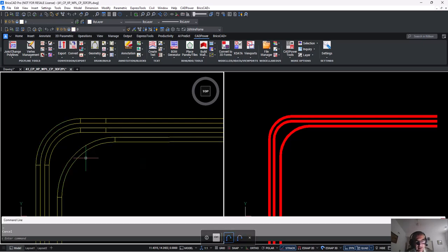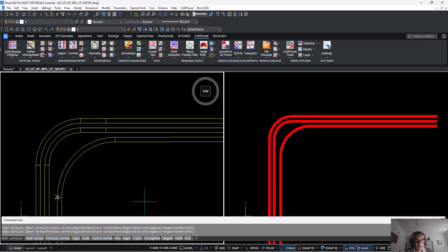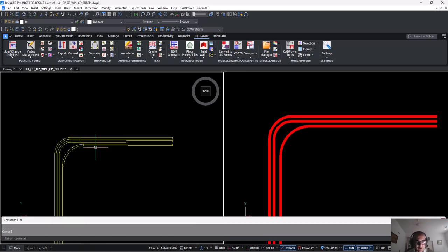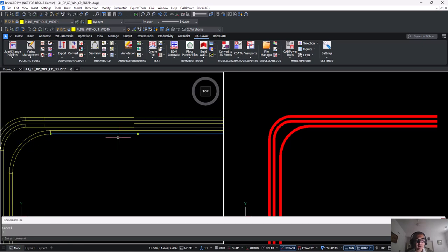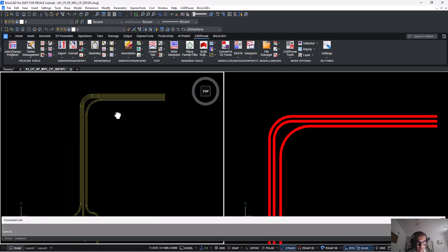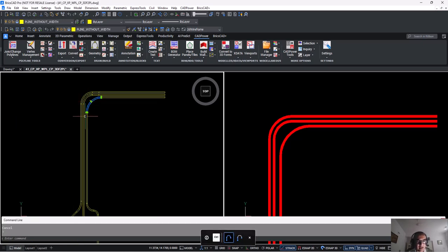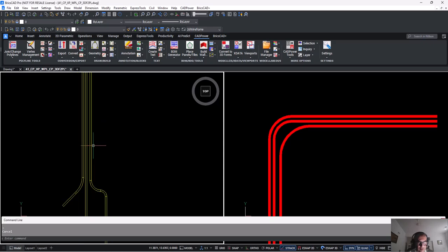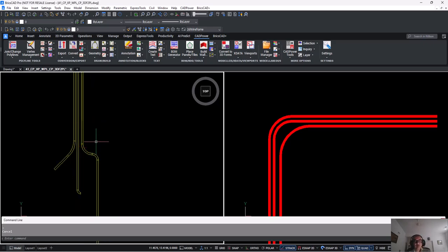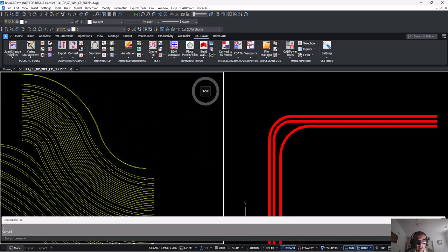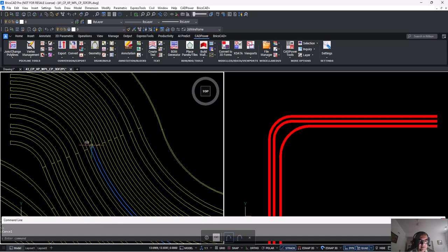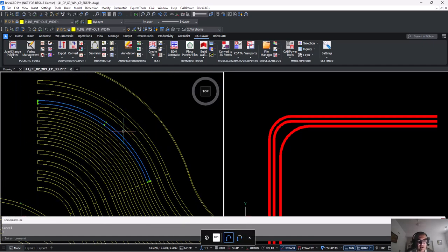There is no width information here. If you run a PEDIT command, you can see there are actually 4 vertices. The straight line polylines got converted into straight lines without width, and the arced polylines also got converted into the respective geometry. It's the same here: everything with arcs got converted into a 4 vertex polyline.